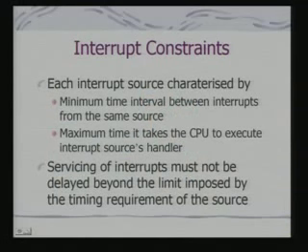So, when I am designing an interrupt service routine, I have to be very careful to check the maximum time that an interrupt service routine can take, delaying other pending interrupts. And by delaying other pending interrupts, I should not miss a deadline imposed by the external world. And this is the key issue which goes into designing an appropriate interrupt service routine.